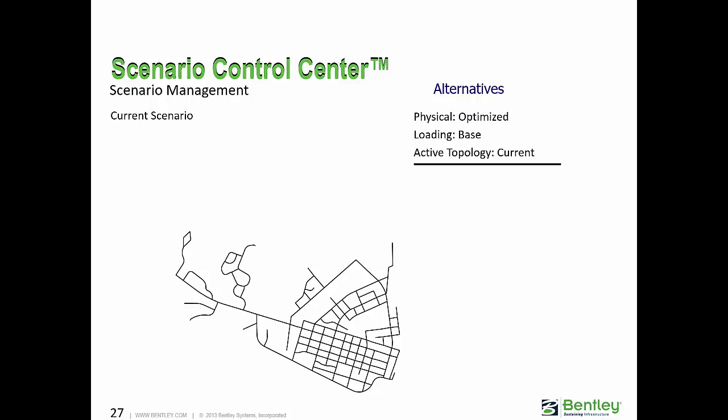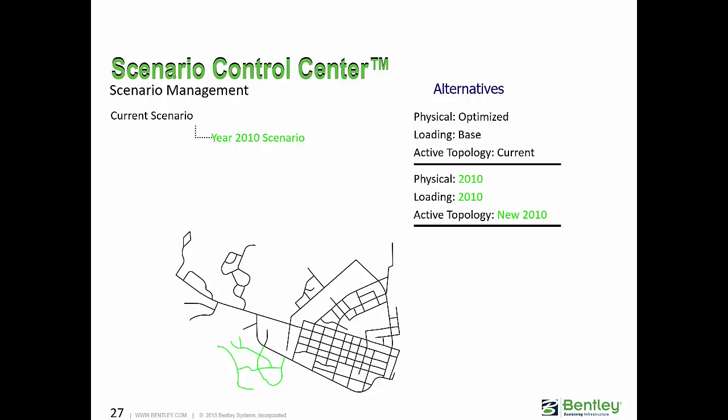So if this is your current network, your current sanitary network, and you want to see what will happen if you forecast the southern expansion in 2010, for example: if you have additional service connections in the southern part of your network, will the existing infrastructure be capable of catering to the additional flow? If not, then what should be done, right?